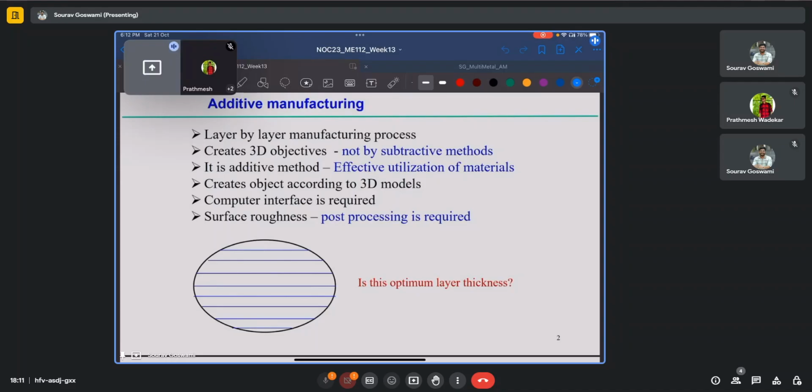So, one of the key aspects of the definition of additive manufacturing is that there should not be any subtractive or formative methods involved. It should be wholly additive. And if you would recollect, we also looked at some of the processes such as laminated object manufacturing, which inherently has a subtractive step. So by default, all laminated object manufacturing processes are hybrid in nature. However, the very pure definition states that there should not be any subtractive methods involved. If there are, then the process stops being only additive and becomes a hybrid process.